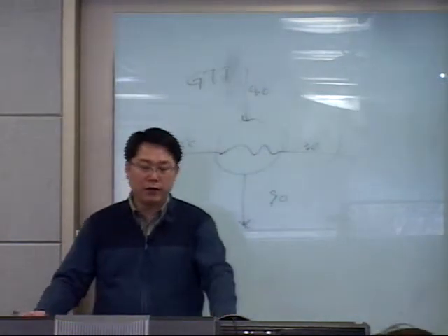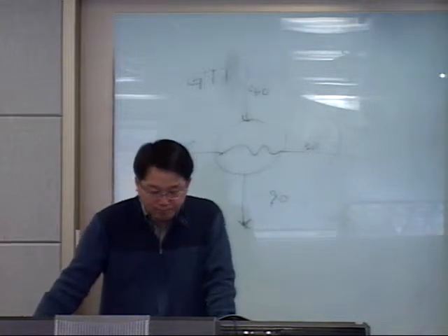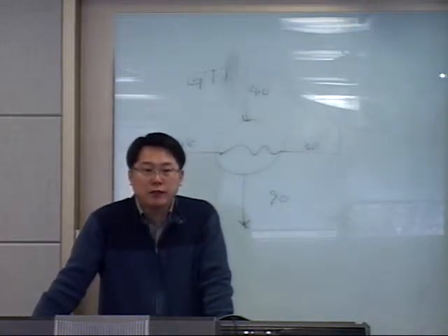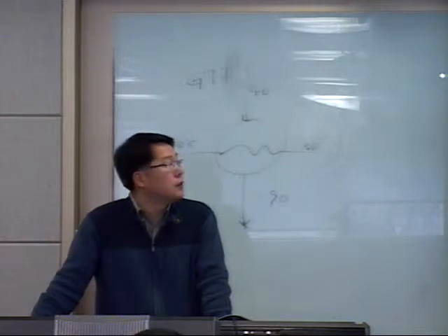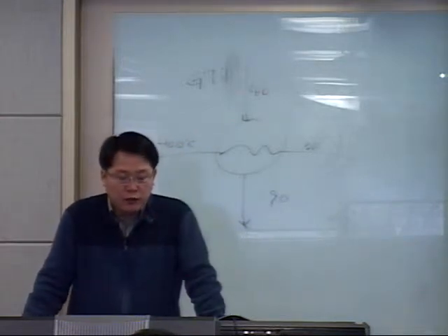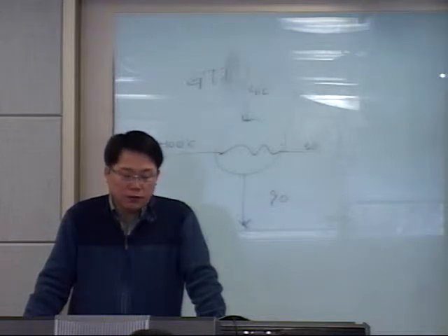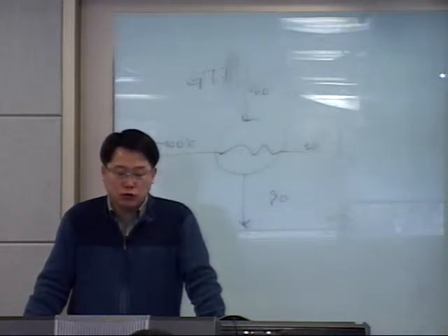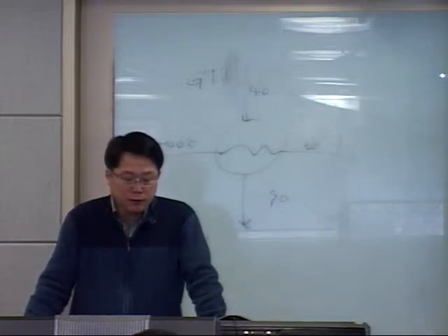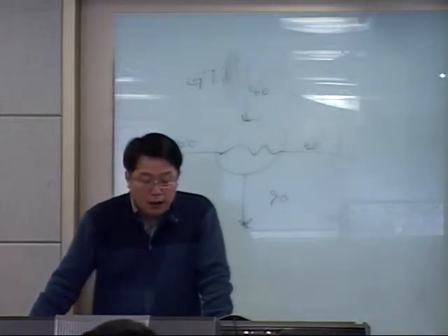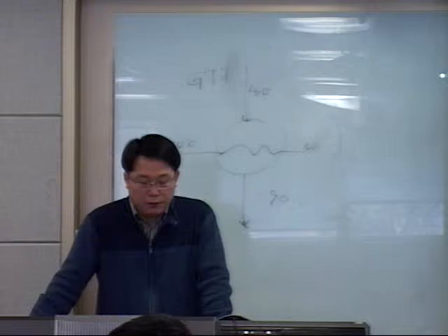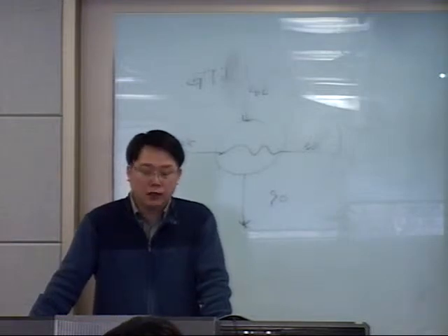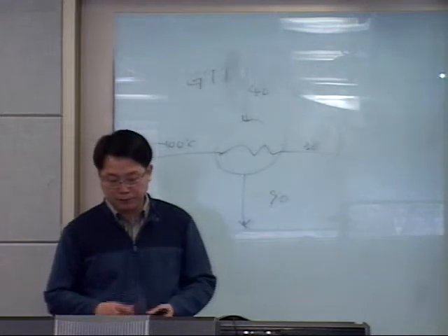There are some thermodynamic questions. Of course, there are a lot of challenges to the system design. But in this class, we concentrate on the thermodynamic questions: energy transfer, heat transfer, and system design. So for convenience, let's divide the system into two. One is the cargo containment system, the other is the BOG reliquefaction system. The cargo containment system includes cargo tanks, pumps, insulation, and headers. The BOG reliquefaction system contains the BOG cycles and nitrogen cycles.